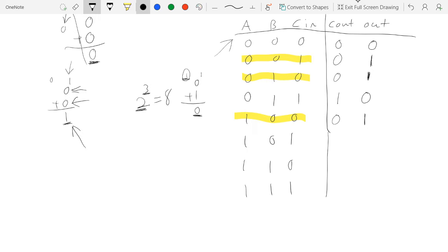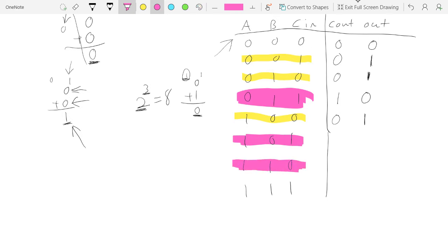Again, I can look at all the cases in our circuit expression where, since we're just doing addition here, this isn't true for all truth tables, but it is for our case, since we're fundamentally just adding up A, B, and C. I can look at all cases where we come up with 2 as the answer. This is 2, and this adds up to 2 as well, 1, 0, 1. And this adds up to 2 as well, 1 and 1 and 0. So I can go ahead and copy this expression down: 0 is our output and 1 is our carry output bit. I can copy that down to the other cases.